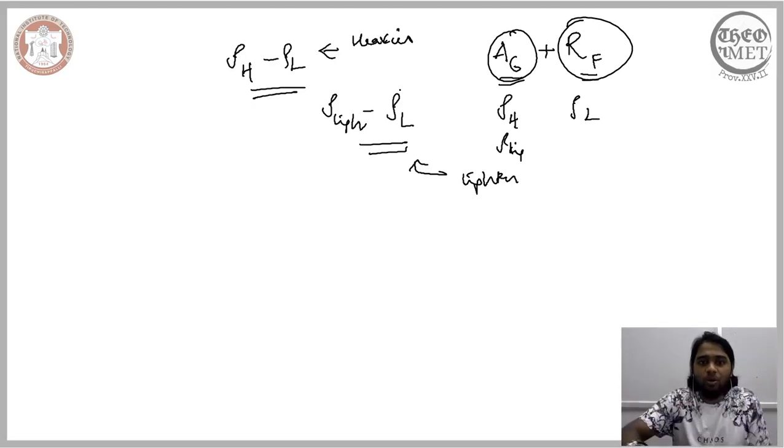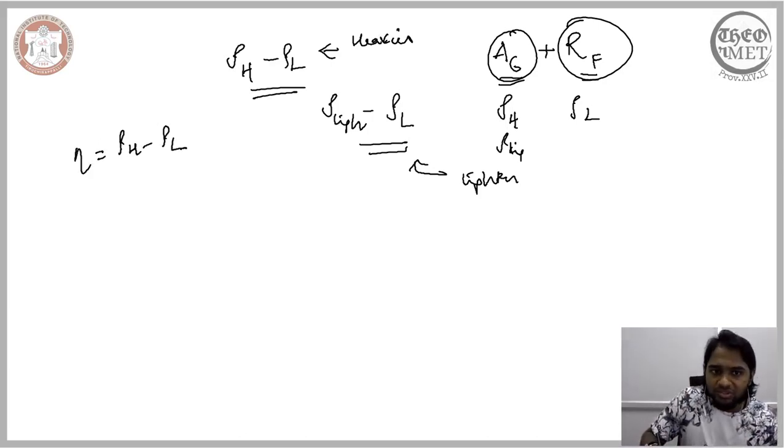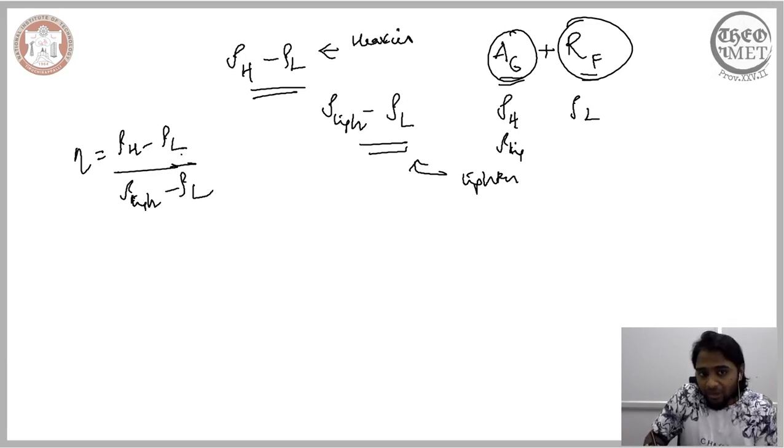And the efficiency of the gravity separation, which is dependent on the difference between the gravity of the heavier and the lighter particle of the mineral in the gangue, is now correspondingly expressed as this relation here. So this is a conceptual understanding of how we arrive at this relation. So density of the heavier particle, density of the lighter particles, and we have the density of the liquid that accounts for the resistance that is introduced by the liquid.